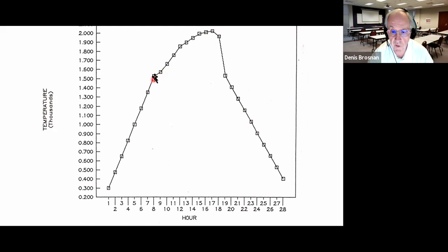If we heat too fast through this area right here, the water vapor and carbon dioxide, CO2, that's formed in this preheating can cause preheat cracks in the ceramics. So it's just a volume change that's causing that. Once we heat up a little more, that difficulty is gone, and we come up here to the maximum temperature